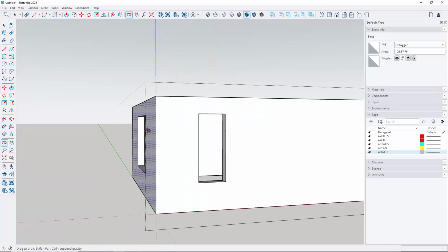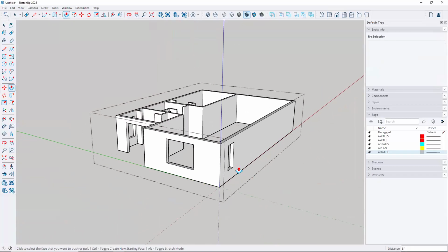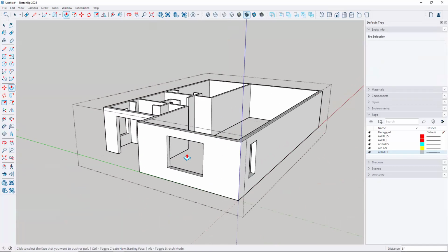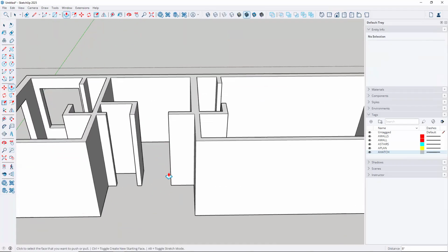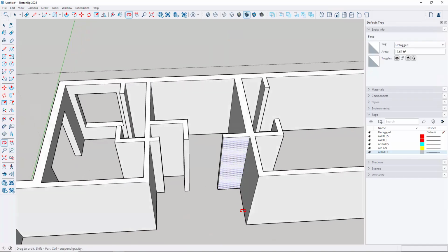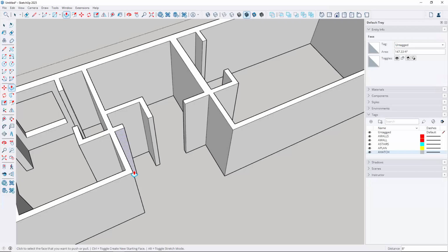So those are different ways of creating openings in these solids. And in our case, we're making the openings because that's where we're going to put doors and windows. So I'm going to come in over here to the inside of my building now. And I know that I want to have a soffit going across here. So since I'm already in my group, I want to show you something, more ways, again, of doing this. So I can draw a rectangle, or I can do this. I can type L, and I'll just draw a line from this endpoint over to this endpoint, like this.